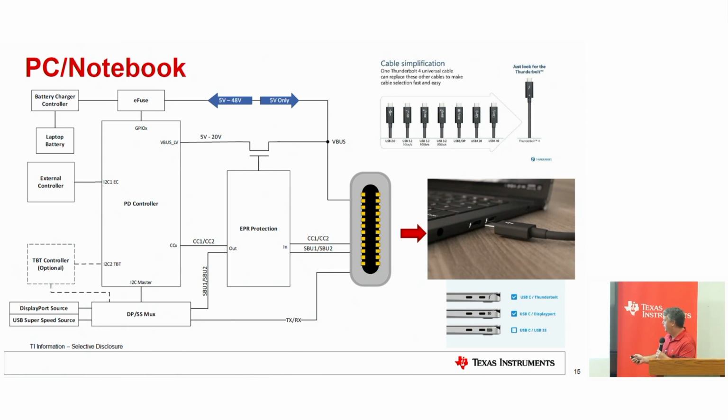I think you guys are going to get all these slides, but I tried showing that, even in the Type-C spec and from the USB on, there's been a myriad of different types of cables. Somebody asked me earlier, what happens if they plug the wrong version of the cable in? As you go into EPR, it needs to be an EPR capable cable. If you want to go to 5 amps, it needs to be a cable capable of 5 amp. The good news is if it's not and you plug in the wrong one, you just won't get that optimal charging or you won't get that power through.